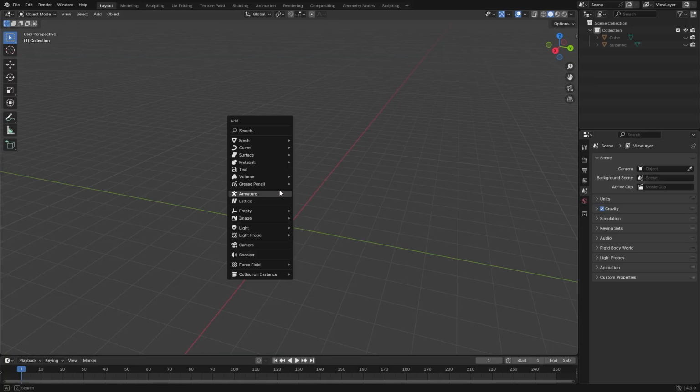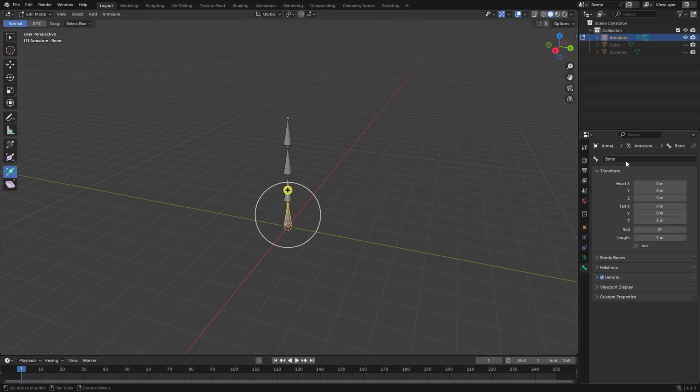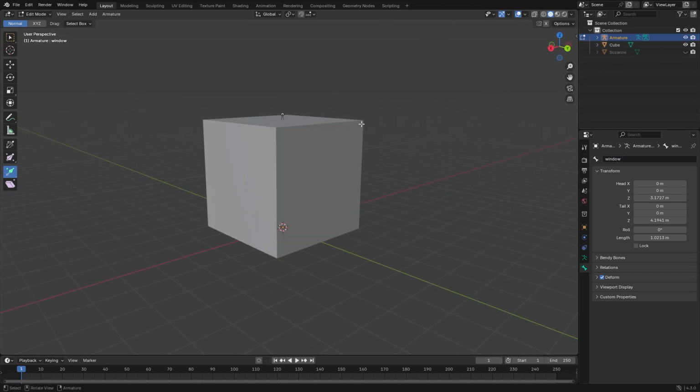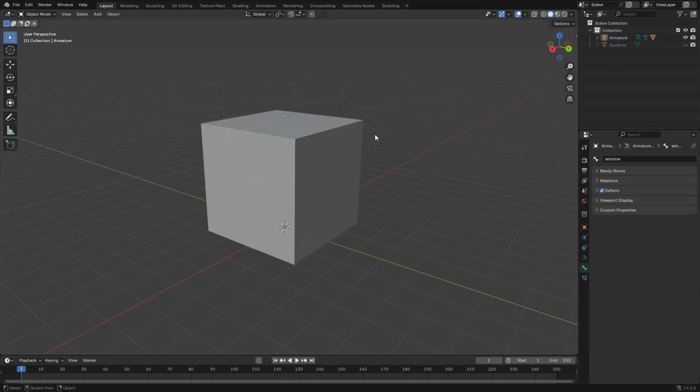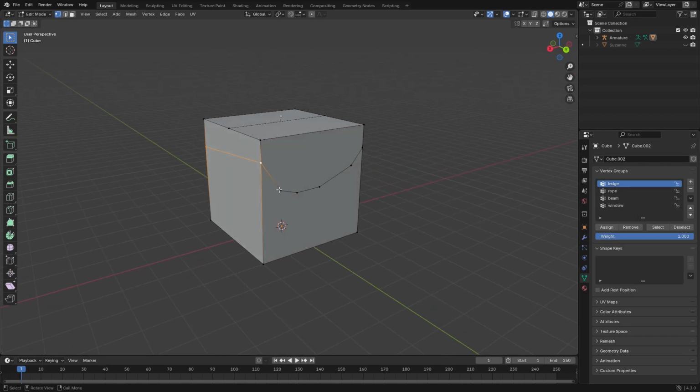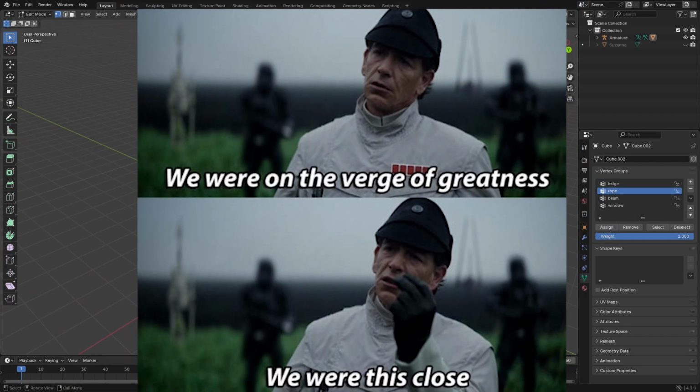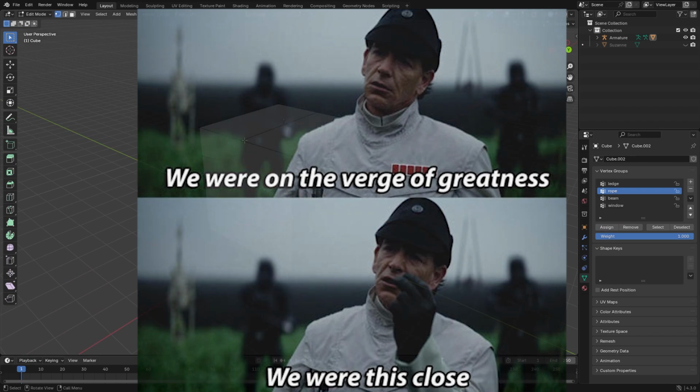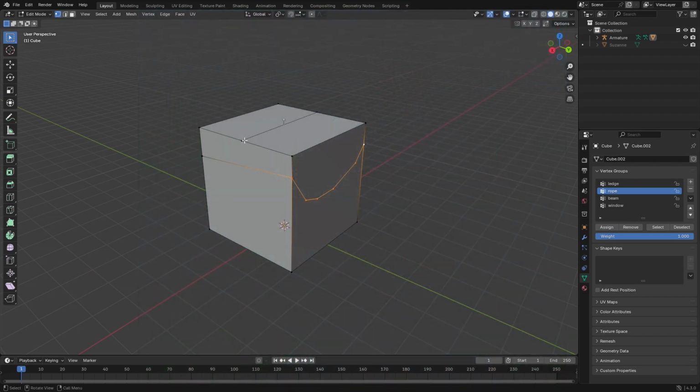The third option is to use bones. Bones actually can be bound to vertices with vertex groups, and this workflow actually looks much more likable than vertex coloring. Just add whatever skeleton, name its bones as your edge mark groups, and then you can just select vertices in edit mode and put them in a group. But this workflow has a big arrow in its knee. Godot and actually most game engines allow only 4 bone influences per vertex. It means that in your marking system you are limited to 4 tags per imported asset. Kinda, as if you ask me. I only try to invent this pipeline and it already tries to impose limitations on me.